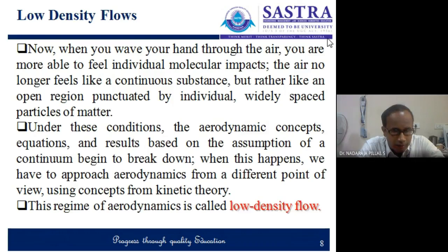We had a discussion on thin shock layer, entropy layer, viscous interaction, high temperature flows, and now low density flows. And the density is quite different, right? At sea level, the density is very high and the mean free path is on the order of 10^-7. But at an altitude of 342,000 feet, we have a mean free path lambda equal to 1 foot.